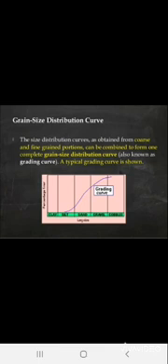You can see in the graph there is a curve that represents the clay, silt, sand, gravel or cobbles, the type of soil that is there, and the percentage finer, right? The size distribution curves obtained from the coarse and the fine grained portions can be combined to form one complete grain size distribution curve, because we cannot say that within 5 meters there are different types of soils; practically it is not possible. So we have to plot a single curve to find the percentage finer and their log size. A special graph is needed to plot the curve. It is your logarithmic graph. You cannot show that curve on simple graphs, right?